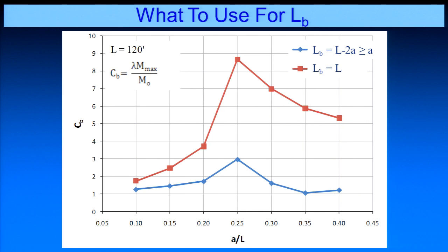But when Andrew was doing his work, one of the things he was looking at was, is the buckling capacity dominated by the overhang, or is it dominated by the region between the lifting points? So he ended up backing out a C sub b from those expressions. Later, when Jamie was working on this, we realized maybe a better approach is to always define our unbraced length as the total length of the segment. That way, if someone wants to change where their lifting points are, all that's going to shift is the C sub b that we define.